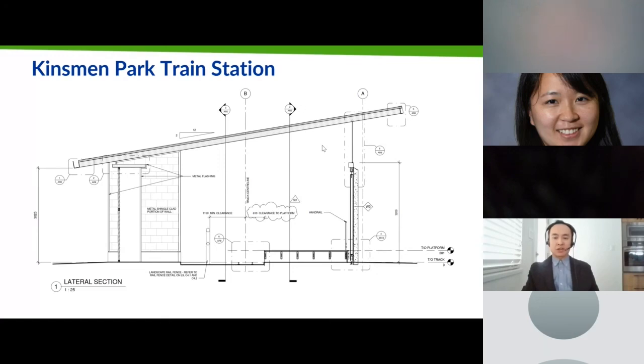At the far right, at the top edge of the roof, you can see that steel trimmer member that's acting as a concealed stiffening transfer beam. At the lower edge, you can see a steel rain gutter that's doing double duty as a stiffening member as well. A pretty innovative way to combine steel and timber to enhance the structural performance.